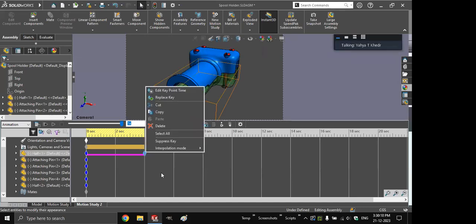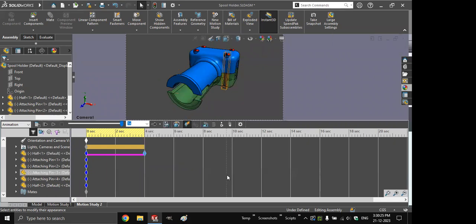Okay, I can change that interpolation mode to something else, maybe ease in or ease out, or ease in and ease out. So it starts a bit slowly and then speeds up and then ends a bit slowly as well. So if I hit calculate, the change is slow, then it speeds up, and then the change is a bit slower once again at the very end. And you can start using these interpolation modes to make the movement more interesting and more easy on the eye, because you don't always want to see things just having a sudden change, but when it's a gradual change, it's way easier and way more pleasant to look at.